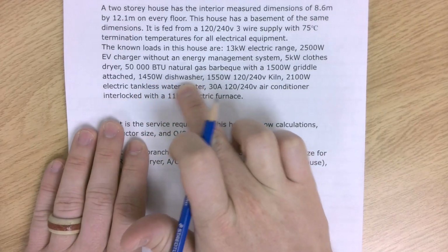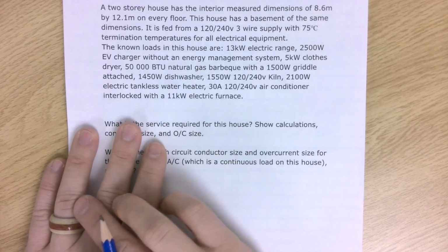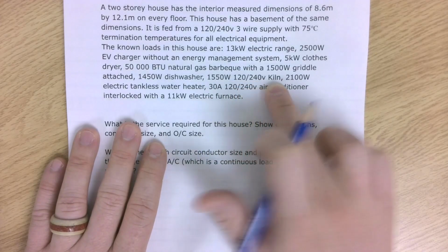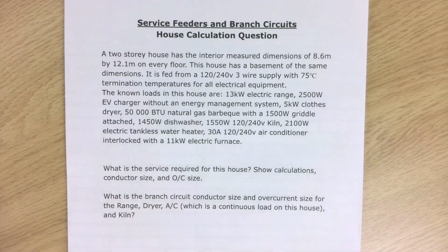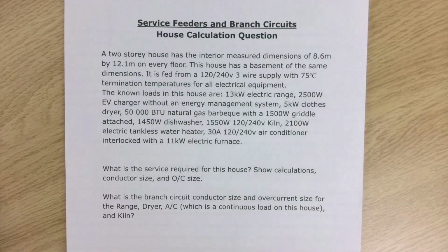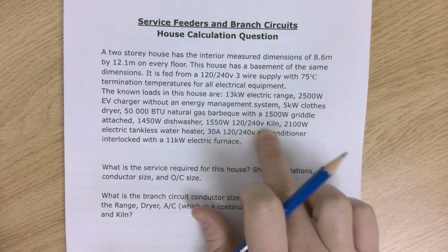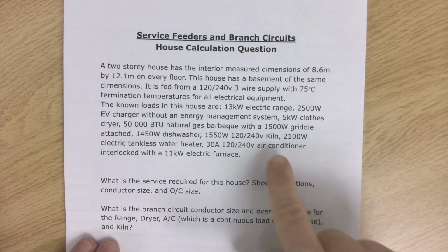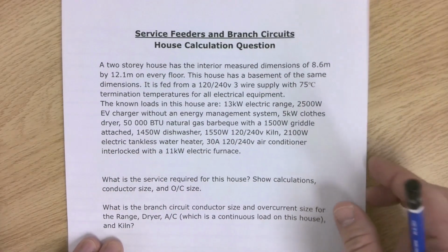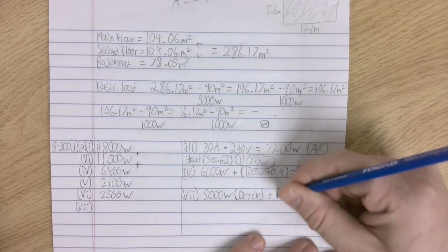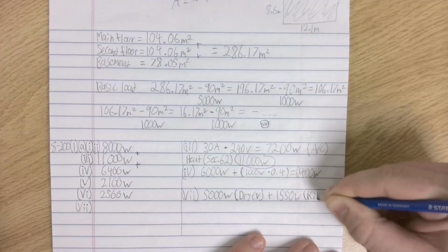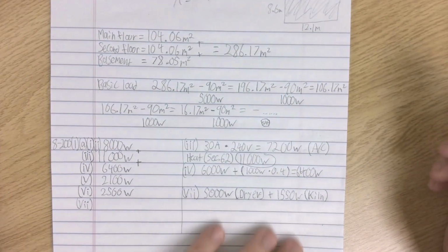1450 watt dishwasher, nope, that's definitely less than 1500. Ooh, but this guy, 1550 watt, 240 volt kiln, sweet. I'm gonna be drying some pottery. I'm gonna dry out some firewood with my kiln. I don't know who has that in their house, but this one has it. It's in excess of 1500 watts, so we're going to have to count it. And then I don't think anything else goes towards it. We already counted that tankless water heater, air conditioner, electric furnace, perfect. So plus 1550 watt kiln. Maybe they have an art studio. They're making lots of pottery.